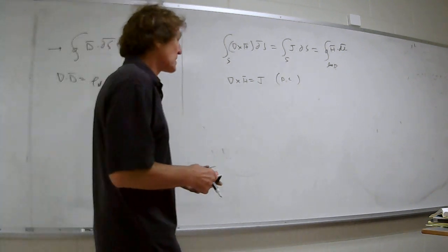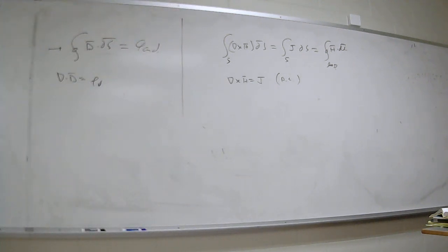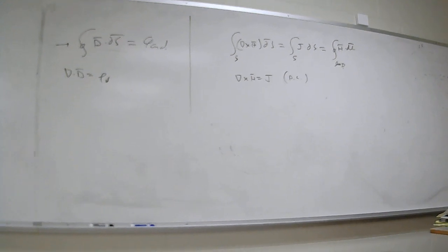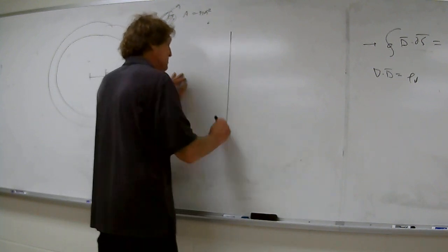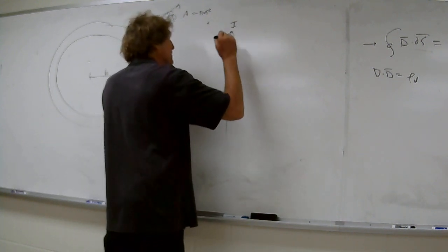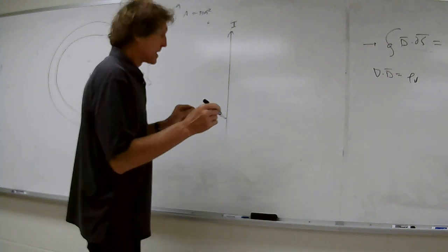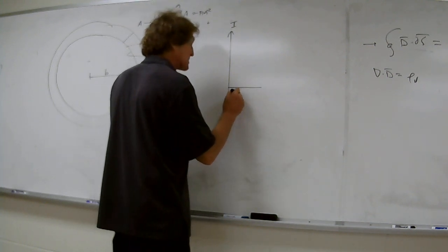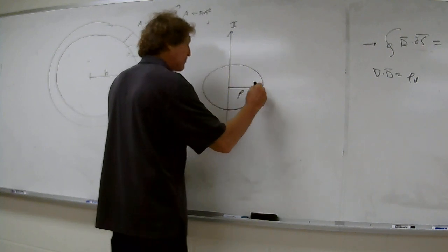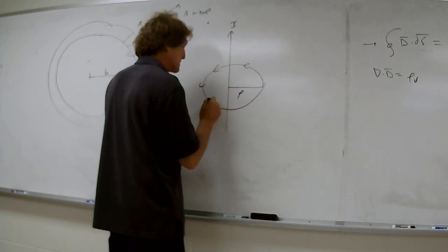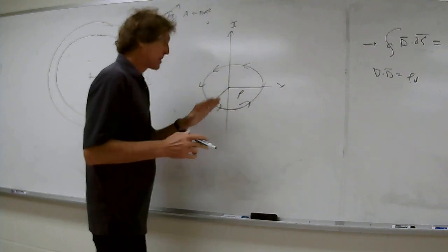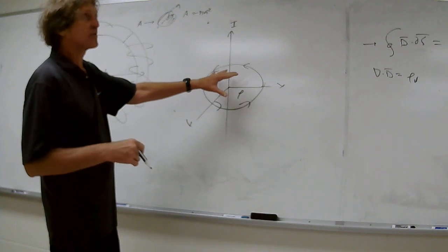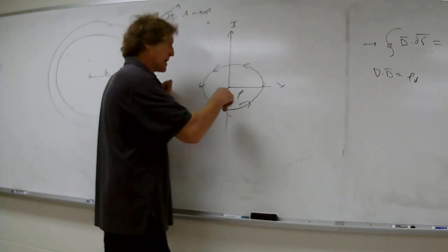Over here, we're going to apply it to this law. Now, if you have something with a high degree of symmetry, for instance cylindrical symmetry, this is the most common one. Let's just assume I have an infinite filament of current I. I come out to a given radius, say rho, and put a loop around there. I'm trying to make this look like it's in the XY plane, but this is X and this is Y. This loop is called an Amperian loop.